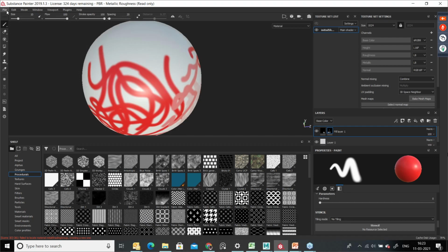So how to import a 3D model from Maya or 3ds Max? First of all, you should unwrap the geometry thoroughly. Okay, then after that you should rename the geometry properly. Each geometry name should be renamed properly, and you should group it properly. The grouping, renaming, and the placement of the geometry in the 3D space, everything should be proper. Then you can export the geometry into OBJ. OBJ format is the best. Even FBX is also okay. So you can export the entire geometry as an OBJ and keep it in one drive as a lower version and a higher version.